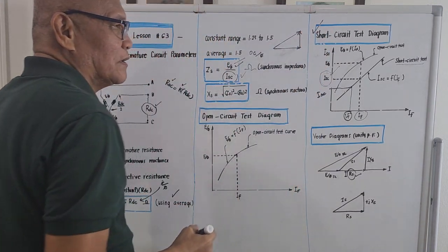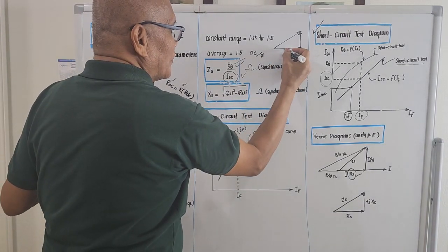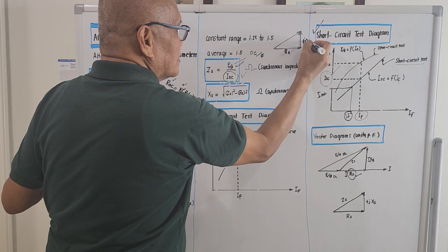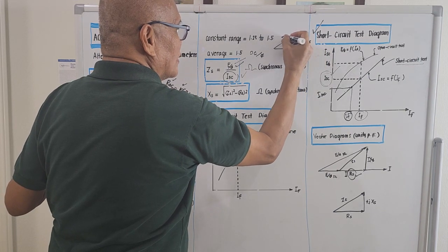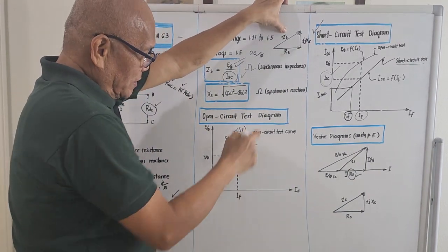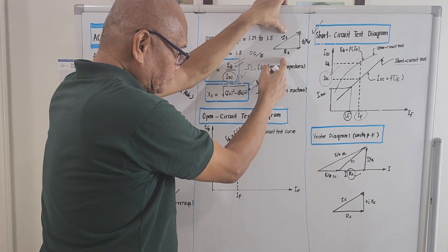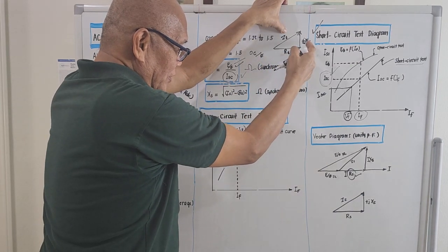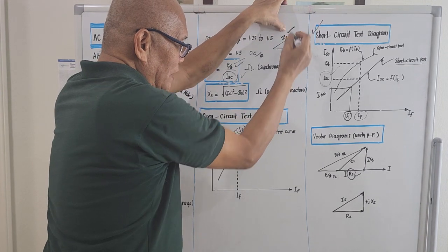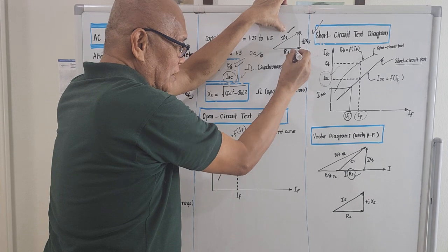Under standard AC circuit, a combination of R sub S plus jX sub S is Z sub S. Synchronous impedance is the synchronous resistance vectorially plus j times the synchronous reactance. So if we know the synchronous impedance, we now know the synchronous resistance.